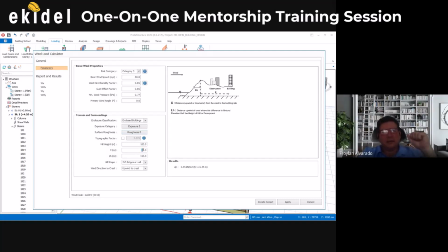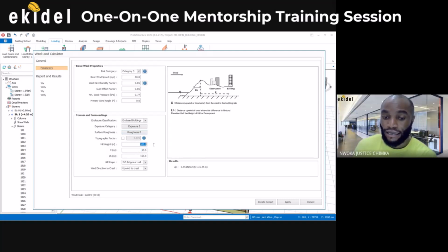Like 10 meters. Exactly. That's what these things are saying. Then if you're building in a mountain area, you can specify the hill height, that's the mountain height. You understand? That's what this means. Because if you have a hill or a mountain, and your building is found at the lower side of the mountain, what it means is that you will be having more of downward wind. Because by the time the wind hits the peak of the mountain, it will have to divert down. So that's what they are asking you here.